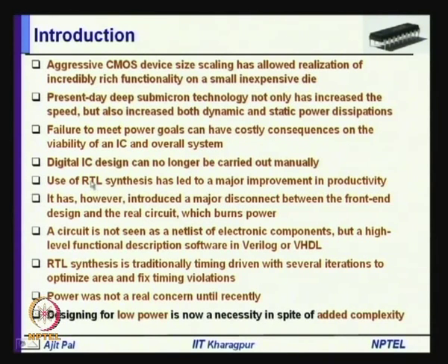So, who is writing a program in Verilog, to him it is no longer a circuit or a net list of electronic components, but a high level functional description software in Verilog or VHDL. So, this has introduced a major disconnect between the actual circuit and the way the design starts. RTL synthesis is traditionally timing driven with several iterations to optimize area and fix timing violations. So, that is the basic approach that is followed in RTL synthesis.